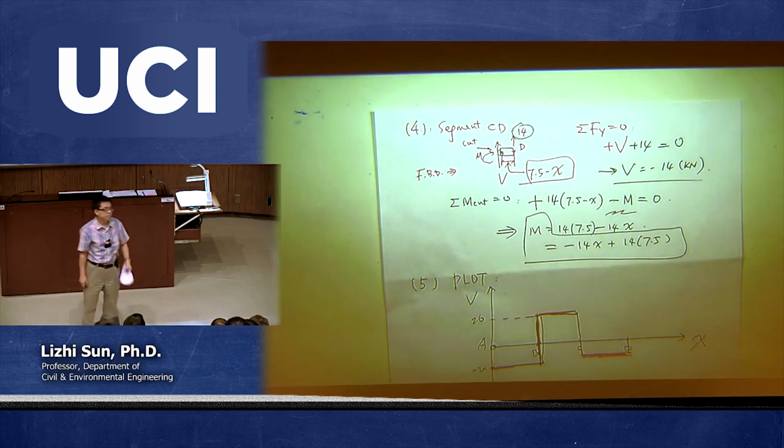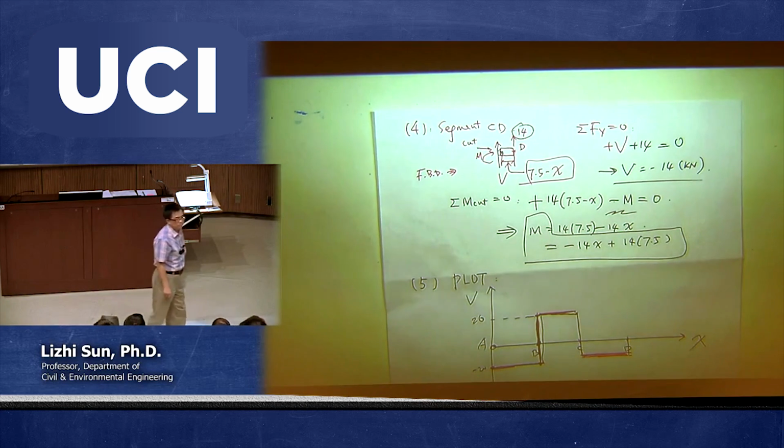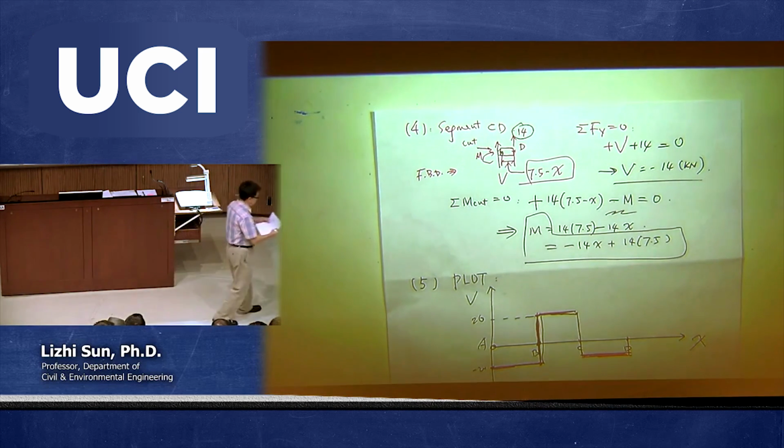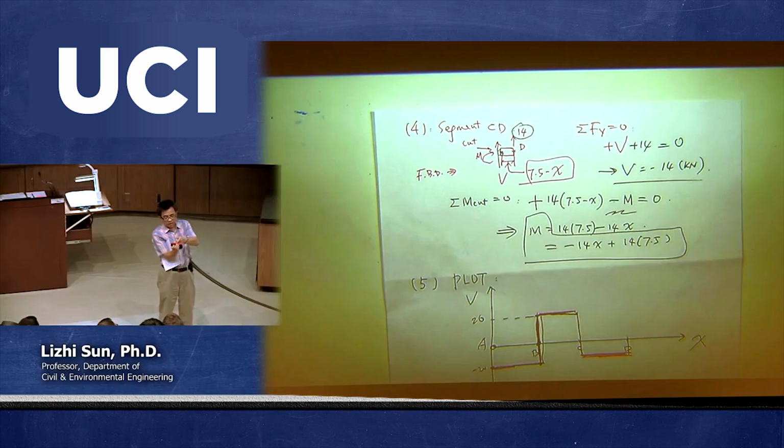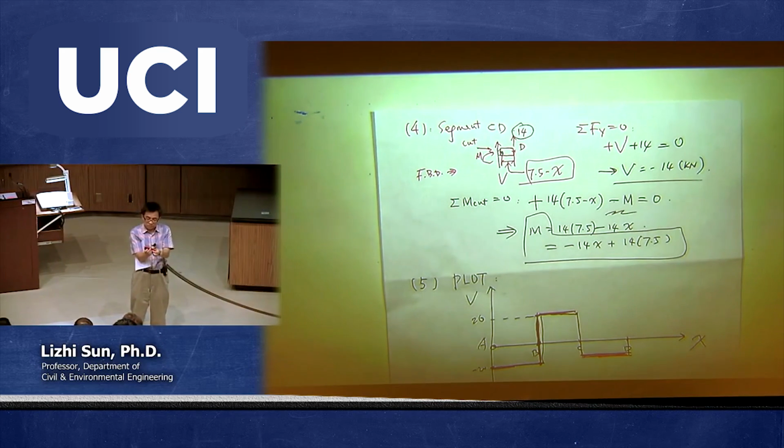Any other questions? Does that mean that all the shear is the opposite sign now, though? Because of one of them? If they're all the same, you said if you followed one up, one down, one up, one down, and if the last one is... No, it's not. It's all consistent. Okay, when you have this beam here, at this point, if you cut it, you have two shear forces. One is on this surface, one on the other surface. So these are always in the opposite direction.